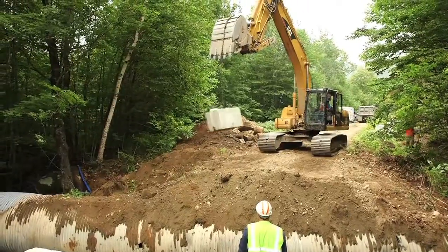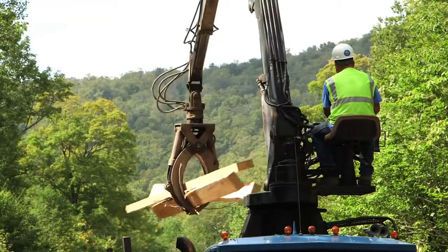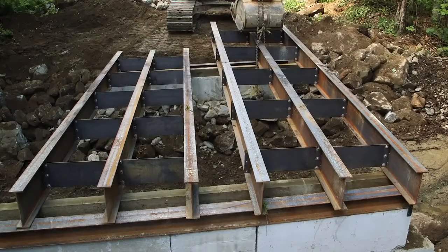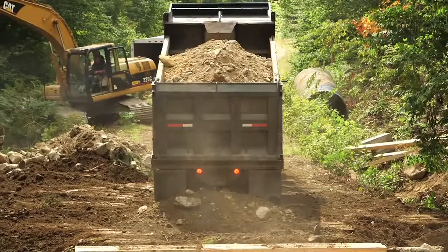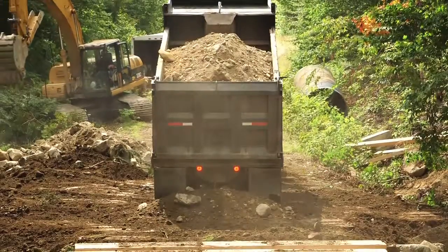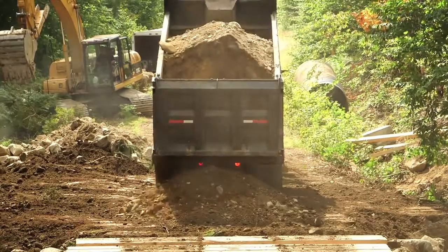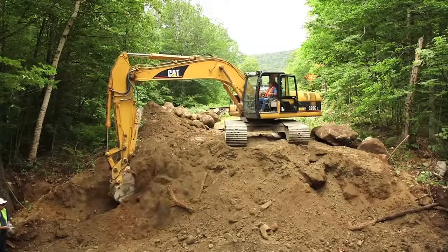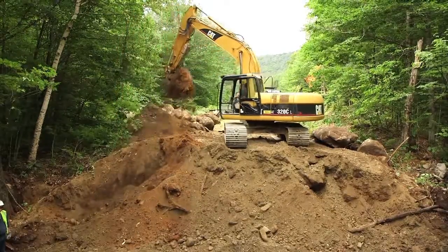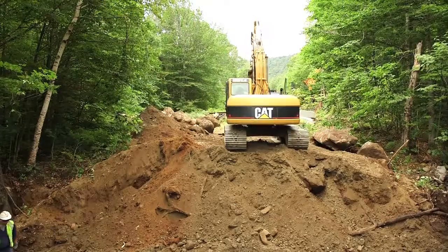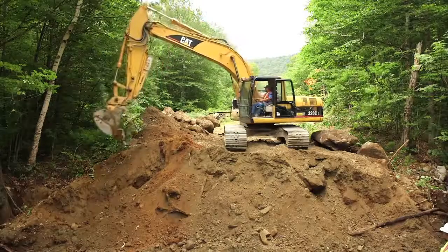For this site, precast concrete blocks were used for the abutments with steel girders and timber components for the bridge deck. The steel girders were pre-assembled in 2 sections in order to minimize on-site fabrication time. Required earth fill or gravel fill needed for the backfill of the abutments and road construction associated with the bridge should be stockpiled on site as much as possible. There are typically on-site storage limitations. However, stockpiling at least some of the earth fill or gravel fill can save time during the installation, especially if the fill source is a long distance from the site.